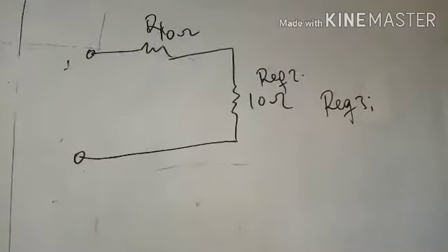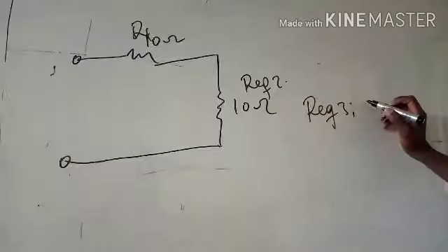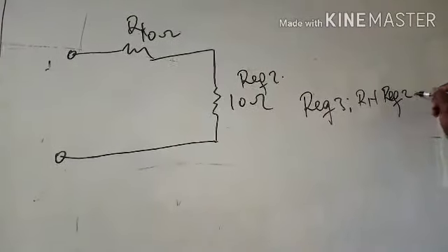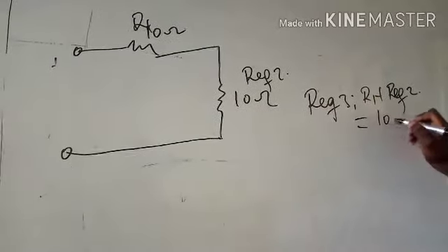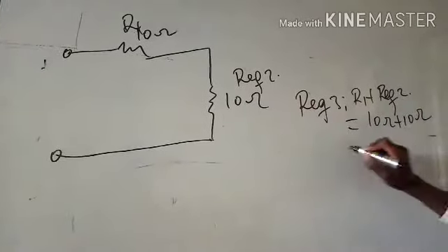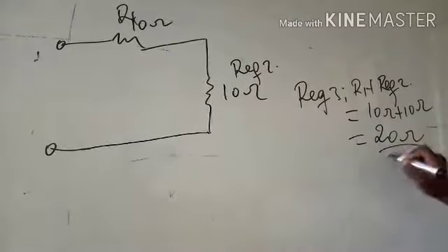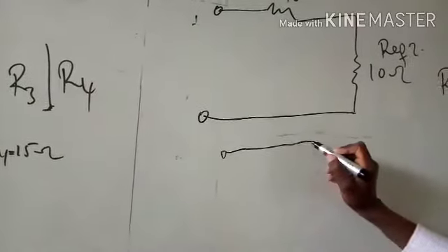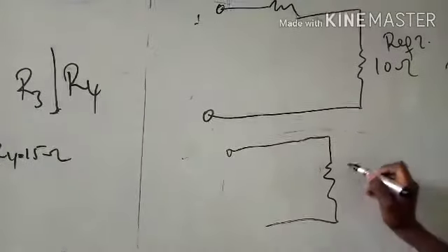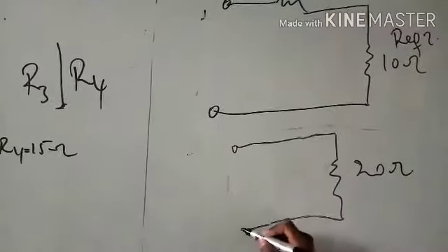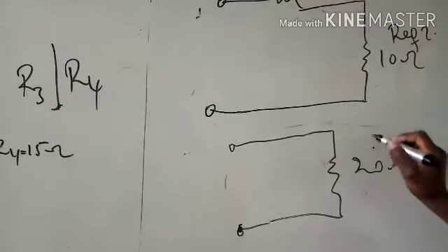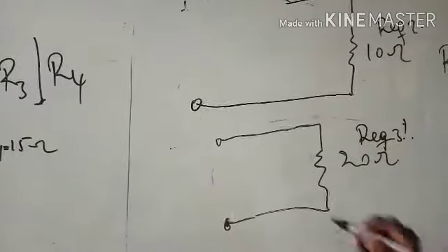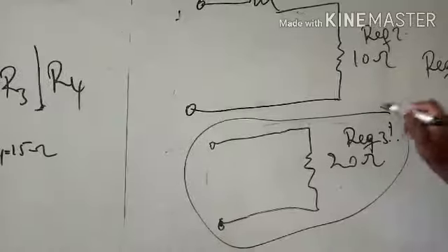It means we will get the final equal to R1 plus R equivalent 2, which will be equal to 10 ohm plus 10 ohm, and then here we get 20 ohm. Then it means our equation remains with this. Here we have 20 ohm, and here we have just our equivalent 3, and then we are asked to find this. It means this will be the solution.